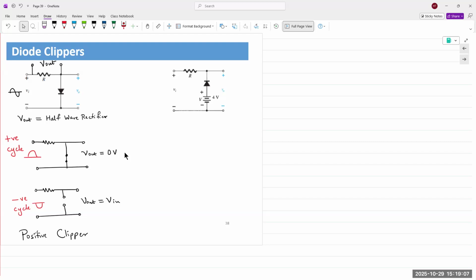Does everyone understand what I'm trying to say? In the lab, they did the half-wave rectifier. You had a circuit, you applied an input from the left, you had a diode as the first component, then you had the resistor, and you took the output across the resistor. But electrically speaking, whether the diode comes first or the resistor comes first does not matter. Yes. The question is, wouldn't there be a voltage drop across the resistor? The answer is yes, there will be a voltage drop. But in a series connection, it still does not matter.